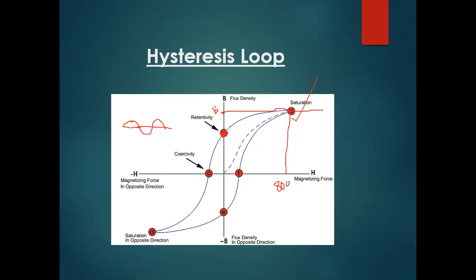So now you are getting this point. Again the current is flowing from this point to the negative side, so we get this curve again on the negative side, at the saturation point. The field is the same, but the sign is negative. Again, current is going negative to positive, that's why this curve goes here again. Here, current is not flowing, this point, and after that current goes here, so this will go here again. This pattern is known as the hysteresis loop.